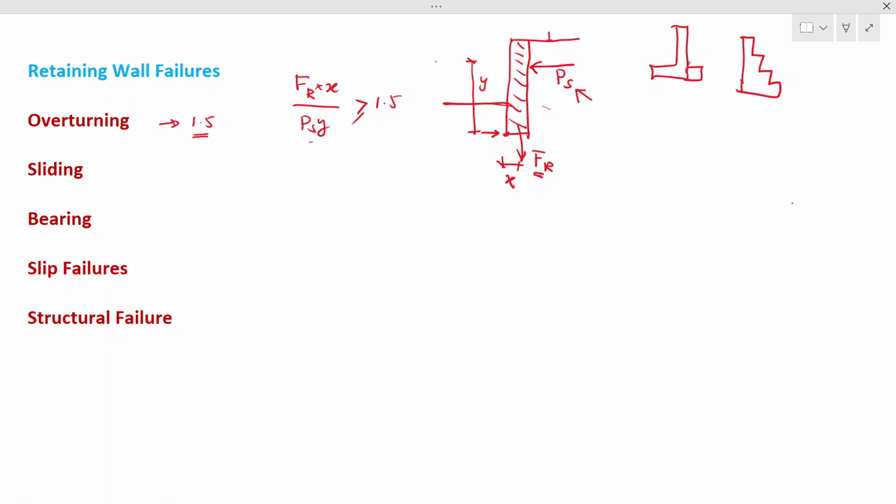Now in this kind of retaining wall, as I mentioned here, the lever arm is a bit different. You have the soil pressure on the retaining wall like this. The restoring moment from the weight of the retaining wall acts somewhere here. Additionally, the soil weight on this extension to this side is applied here. All those combinations make the retaining wall stable.